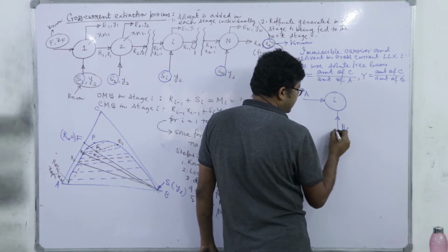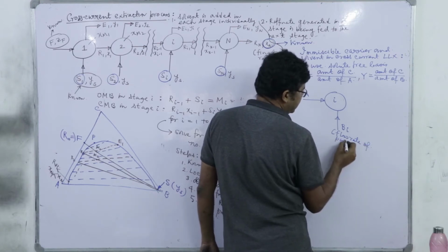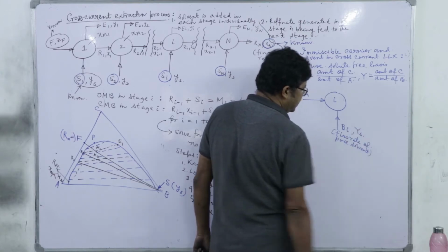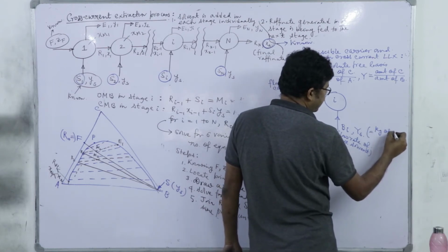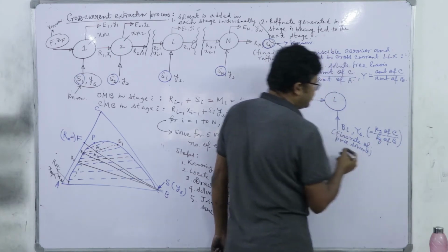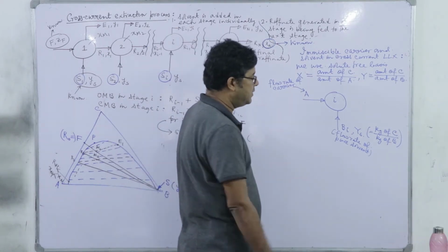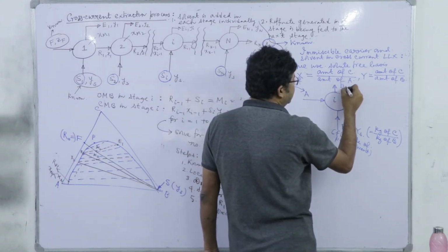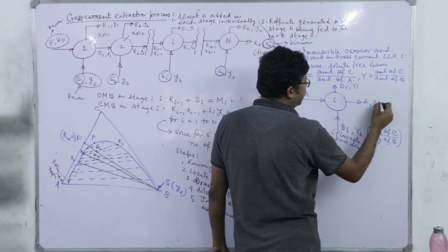That's a flow rate of pure solvent, and its composition capital Ys, right? So Ys represents what? Kg of C per kg of B, right? Why? Because the solvent is regenerated, there may be some amount of C present in this solvent which we are charging in that system. So here we will get Bi, Yi, and very similar, it is A, Xi.